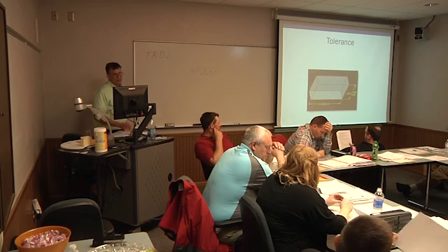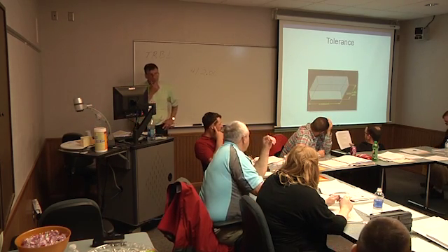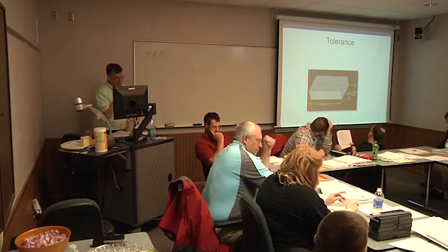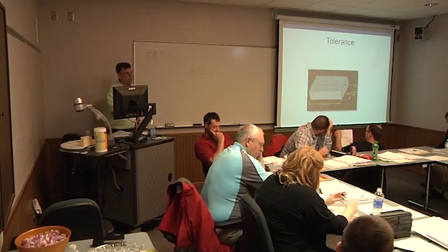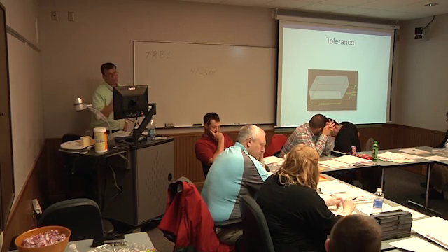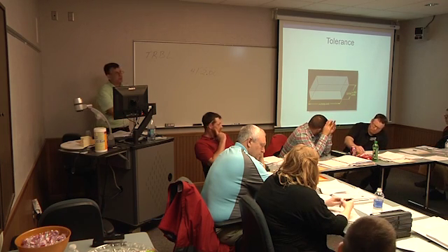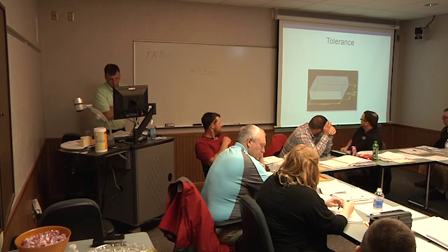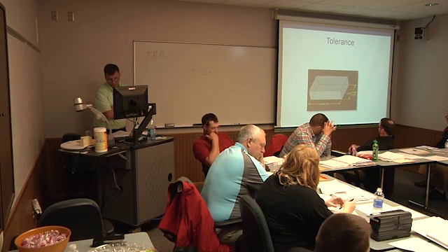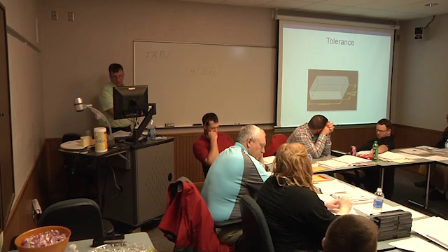I've talked a little bit about tolerances. We were working with tolerances when we were using the calipers and the rulers. And tolerances, that's the amount of variation that's allowed in measurements and in quantities. Just looking at the example here, the width tolerance for the box in this illustration is plus or minus 0.005 of an inch. And the actual width is 4 and 6/1000 of an inch.